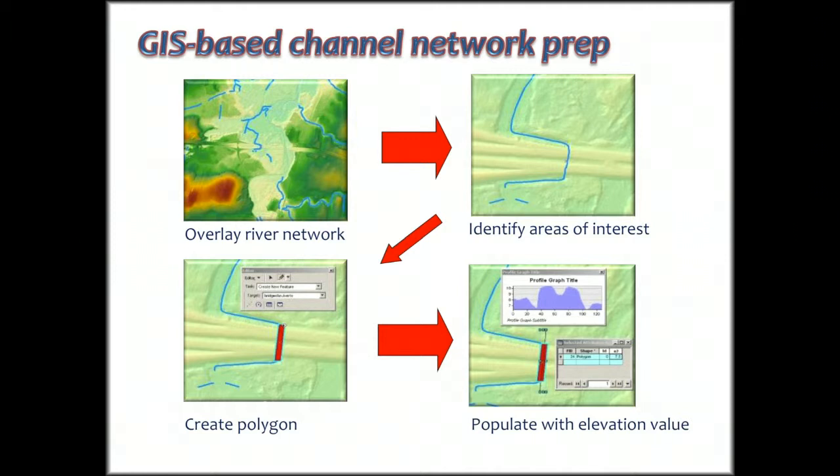And to illustrate that point, here we see a highway crossing. We've got a river here, we've got a highway crossing here. At this resolution, that highway crossing creates a dam or a barrier to flow. Now if we just run fill sinks, what's going to happen is this upstream depression, this channel, will just be filled up. Now it'll create probably a hydrologically reasonable map, but the channel locations will be in probably the wrong location.